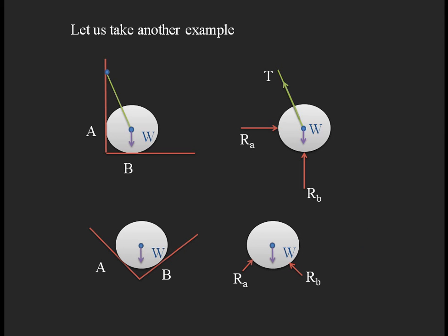Now, I have taken a circular body. We can take any shape of body, resting on any particular object or place, or in between any two components. Whatever the forces may be, by isolating that body from those supports and elements, we can represent the reaction forces acting on the body. That is the free body diagram, which is used in engineering problems to solve for required things, maybe forces or distances or moments or whatever is required. We use free body diagrams.